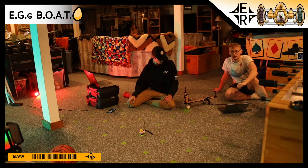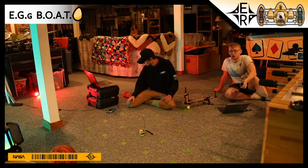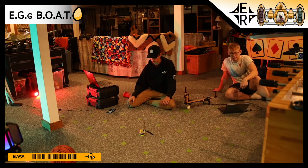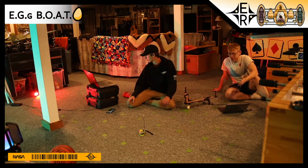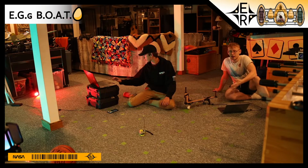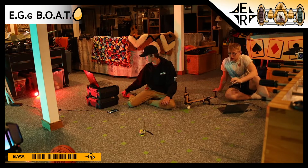Because up until then, I was building the antennas based on how they should work theoretically, and then testing with a nano VNA, a vector network analyzer, which would tell the properties of how well it'll be receiving a signal at a specific frequency. And everything seemed fine, but we hadn't had a beacon to test it, so when we got it, that's what we were mainly doing. And then testing the filtration and the amplification as well.